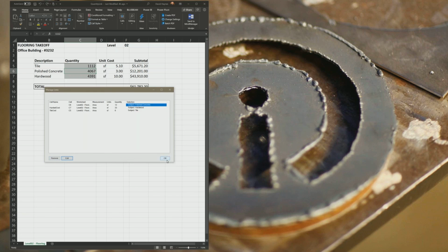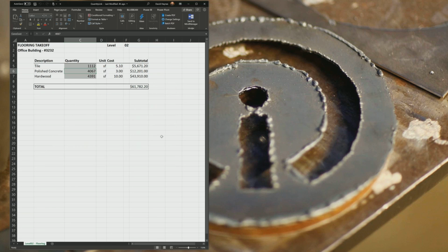And then the last question that came through: is it possible to make a hollowed out polygon? My assumption is you're probably doing an area of a room, but there's a column in there and you want to subtract that out. And the answer is yes. There is a place to subtract when you're doing the areas. And if you ever get a chance for some fun stuff like dynamic fill, there are ways to account for that kind of hollowed out area.